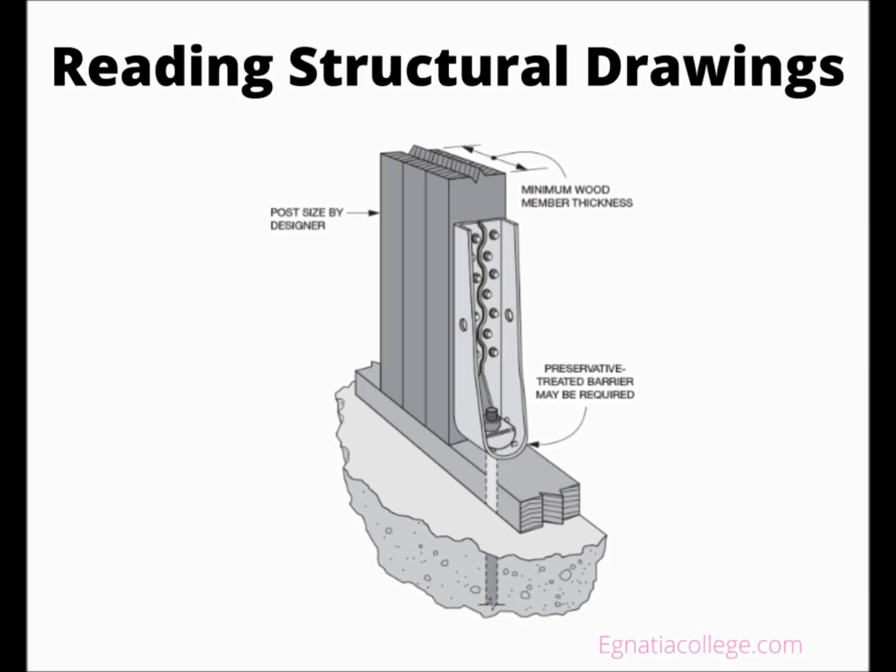To add even more strength to the slab on the Urban Quartz project, a process called post-tensioning is used in addition to using rebar. Post-tensioning involves the placement of a grid of plastic-coated cables in the concrete forms prior to concrete placement. Both ends of each cable penetrate the form and extend past the edge of the slab after concrete placement. Once the concrete is placed, it is allowed to partially cure, usually about 7 days or until a specific compressive strength is achieved.